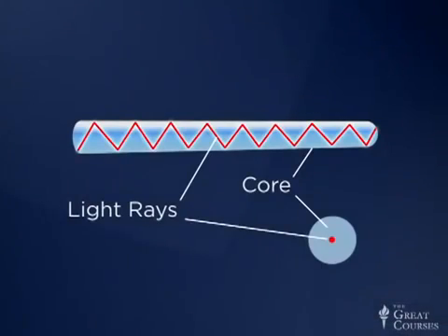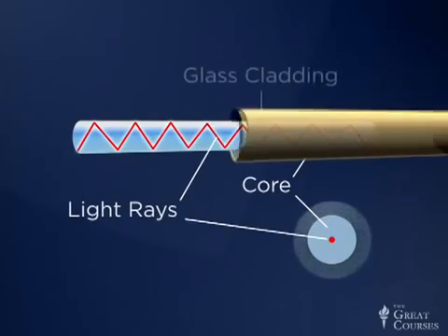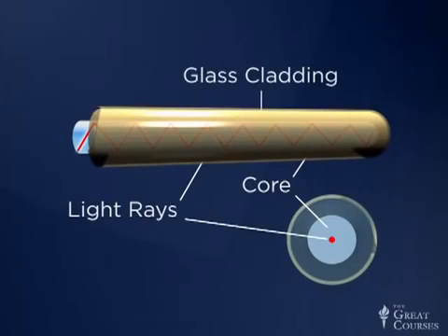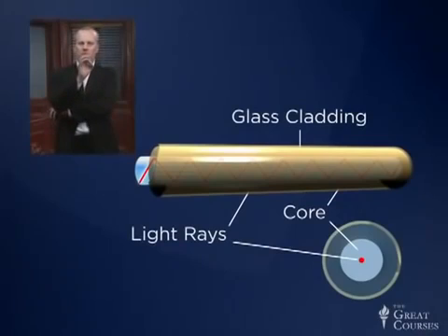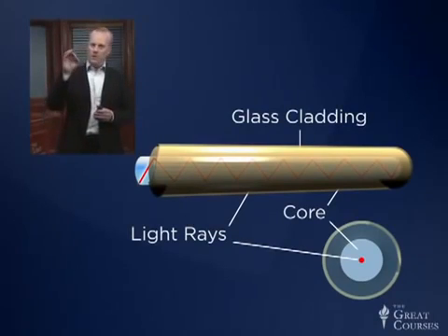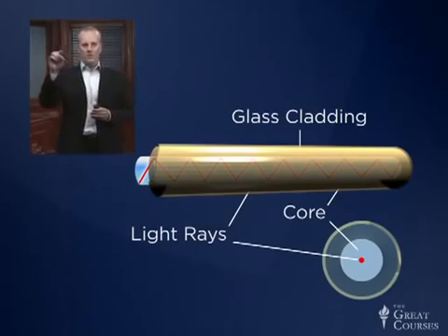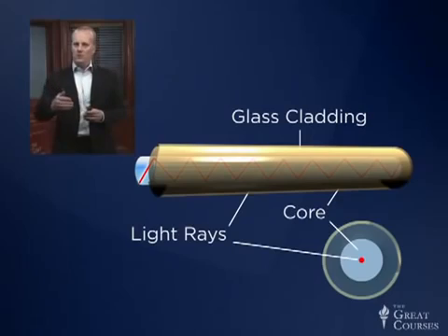In fact, we call optical fibers, based on this glass cladding and also a glass core, single mode fibers because there's only one angle at which the light can bounce. We design the shape of this core, which is cylindrical, and we design the optical properties of the cladding that wraps around that core such that light propagates with only one bounce angle and consequently with a single speed, with a single velocity over these very long distances.